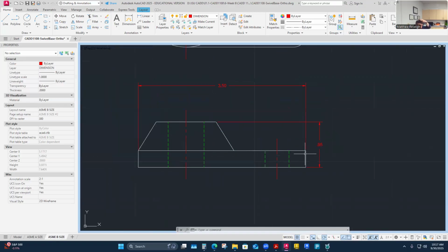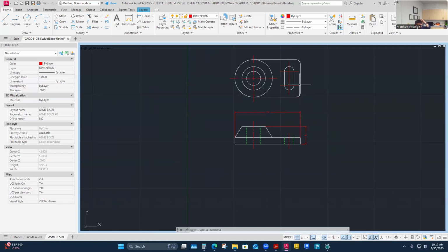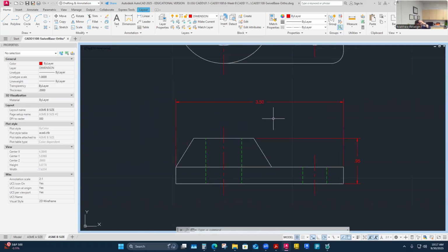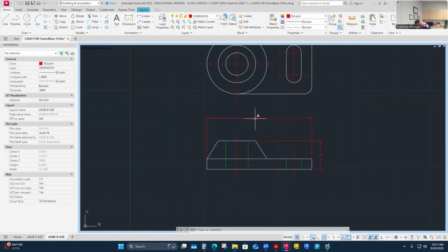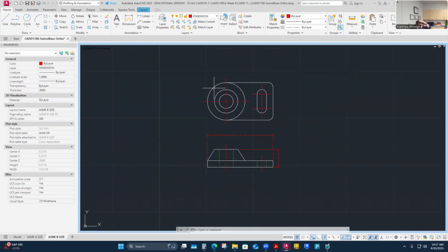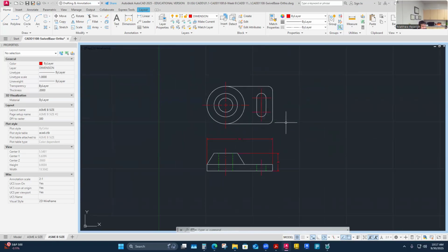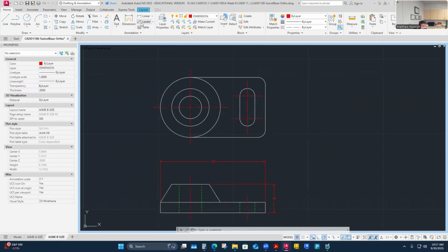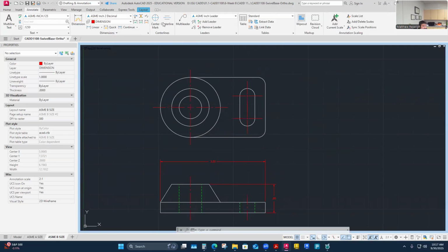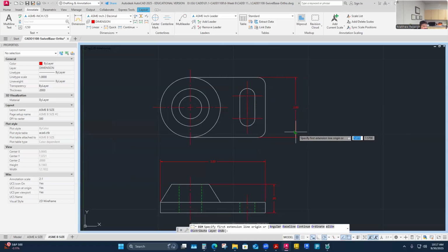It's not bad, especially where I've got such a big right side surface here. This could be a good datum. So technically, in the event that this did become a controlled critical hold dimension, I'd probably base it from here over to there because this is all radiused out to this end. And then I just need the depth, which I think is a great place for that. That's going to be the top view for my overall. Considering this one here is a great one, I'll probably do that there.